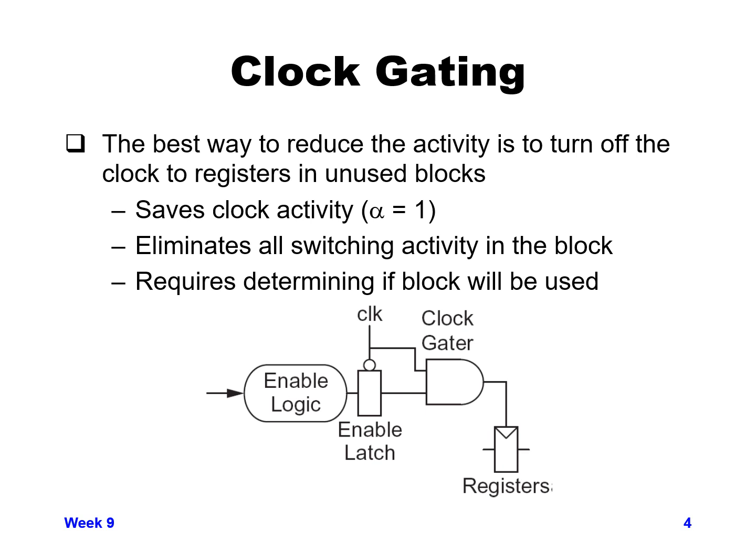going forward, anytime the clock toggles, if the enable is low, the output of that AND gate will not be toggling. So none of the downstream registers will toggle, which means none of the logic coming out of those registers is going to toggle, and your activity factor goes to 0 for whatever period of time you have the clock disabled in effect.